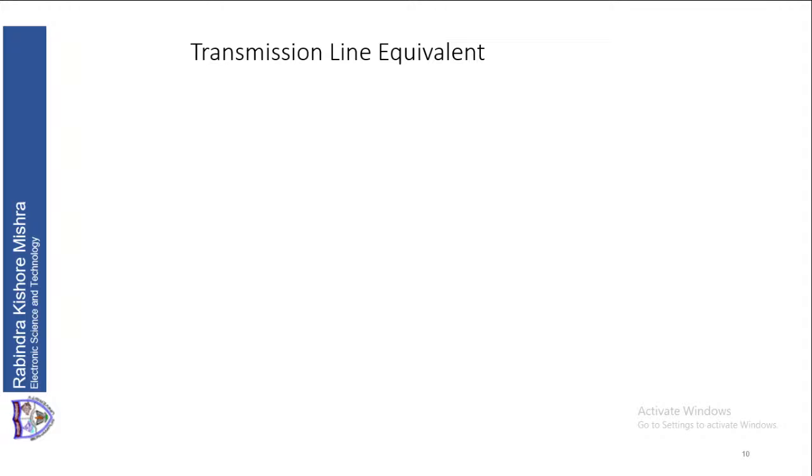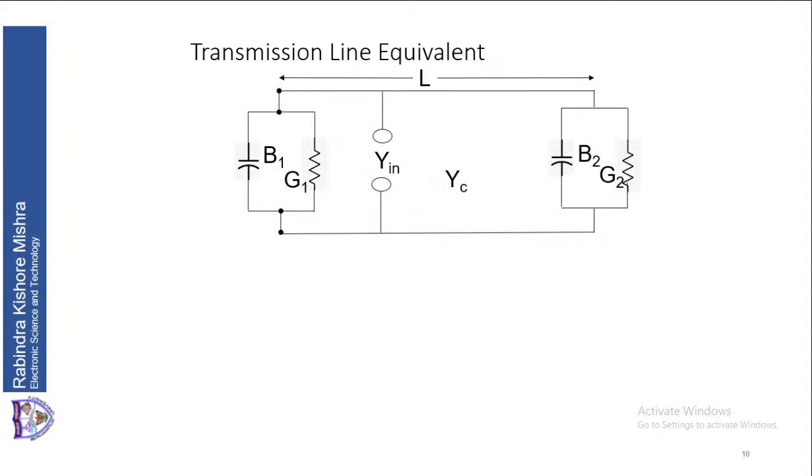Now, to analyze the antenna, we require a model. We use the transmission line model, which is in our course. For the antenna, we can assume that there are two apertures at two edges. So the two apertures are connected by the patch. The patch is a conductor. The patch connects the two apertures. So we have two apertures separated by a patch. The patch is a connector and the patch is a microstrip line. We are using a microstrip structure. So it is a microstrip line. Microstrip line is a form of transmission line.